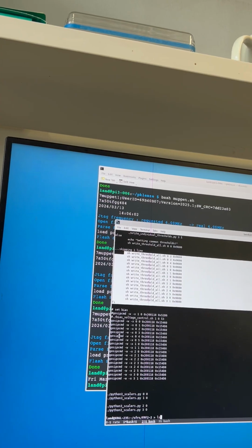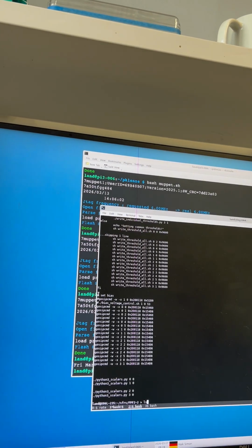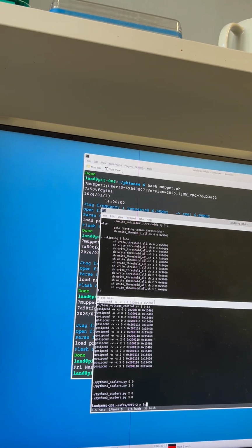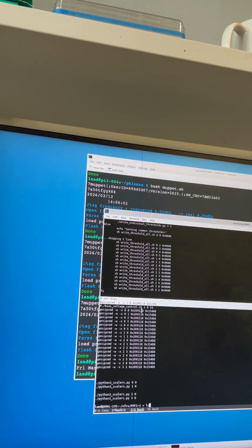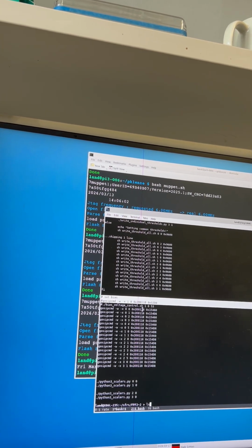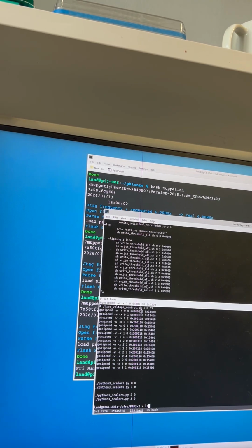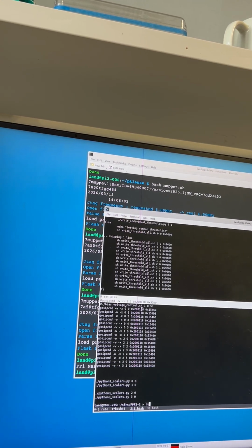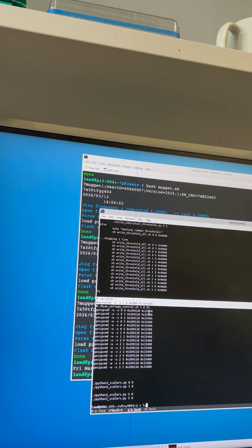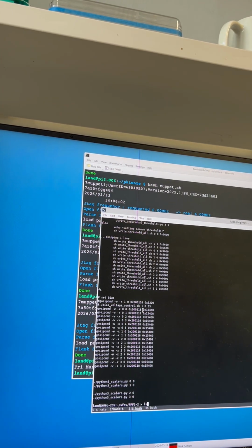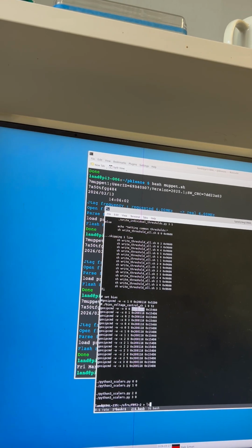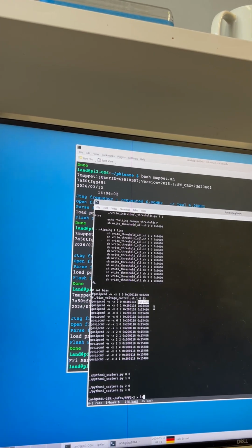And then the bias. You know that these IPMs have a bias from 52 to 55 volt or something like that. And we write it in hex numbers. So every board in this address we write the bias.